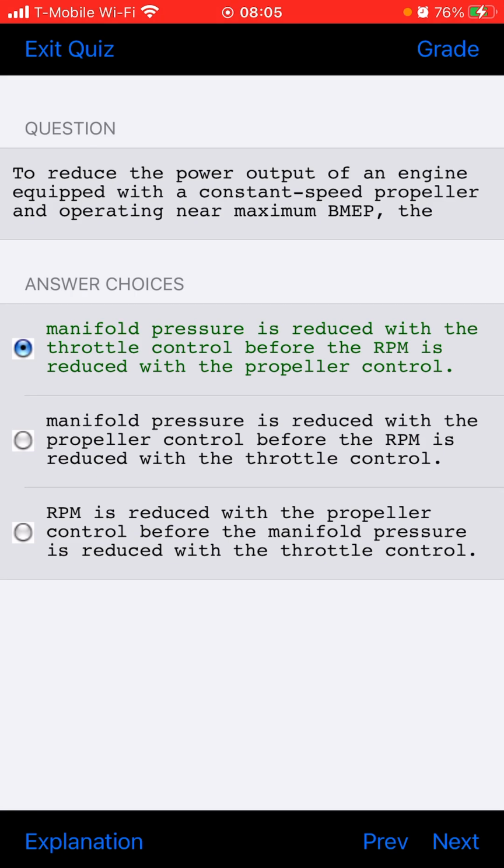If the intake valve is open too early in the cycle of operation of a four-stroke cycle engine, it may result in backfiring. The intake valve opens when the piston is moving upward at the end of the exhaust stroke.